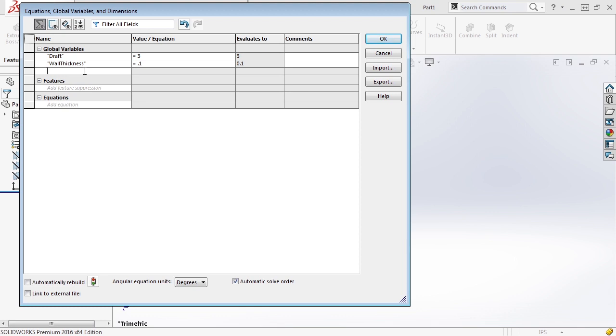Now, whenever you're designing a molded part, and again, this is theory that you're going to have to know once you start to go forward and design your own molded parts, but just for the purpose of our video, I want to make sure that you understand what we're doing here. When you design a molded part, the outside of the part is going to have a consistent wall thickness. That's extremely important that the wall thickness is consistent throughout your part.